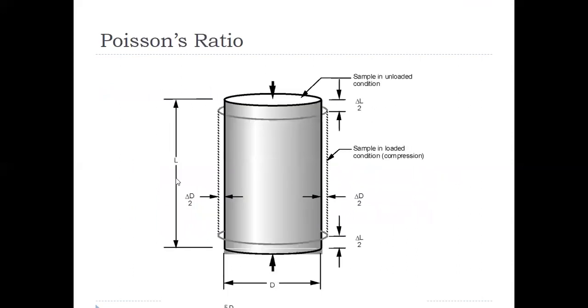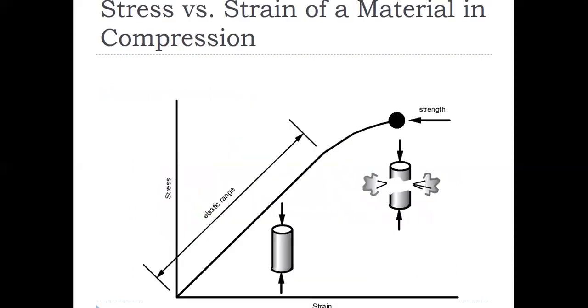So, another terminology you are going to learn is, now let's define this stress and strain. For example, if a material is subjected to a continuous load or compressive load, as you can see, the point where stress is directly proportional to strain, or the linear part of this behavior, is called the elastic range.